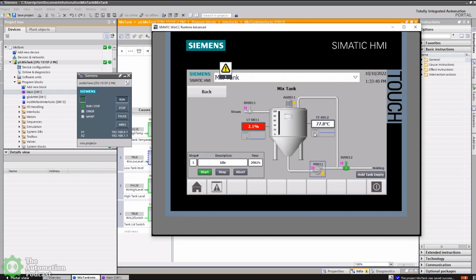That's really an advantage. Even if you just had the basic version of TIA Portal, you're going to have the basic version of WinCC for the basic panels. So you'll be able to simulate the HMI. You have PLC Sim to simulate the PLC. So you can test everything out right on your computer. It's just a great value. And then, of course, you also have the other packages as well for the comfort panels and the unified comfort.